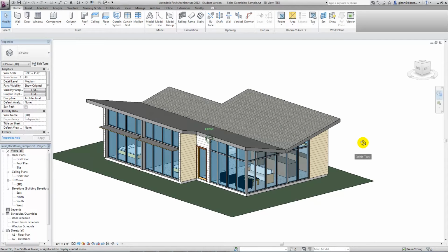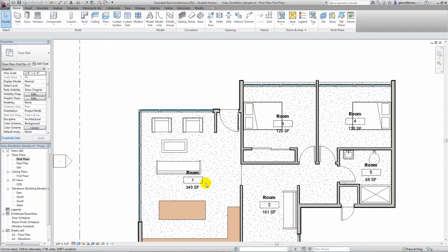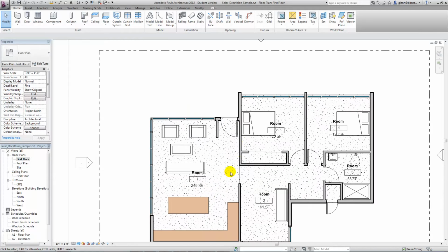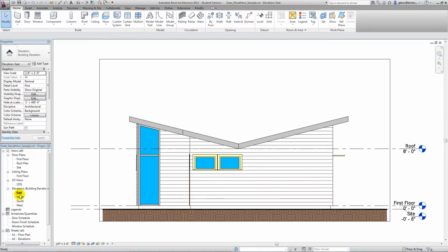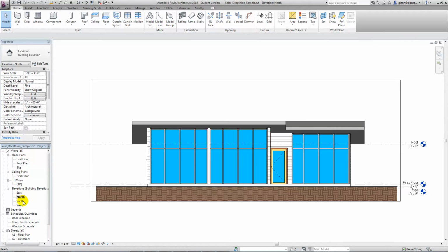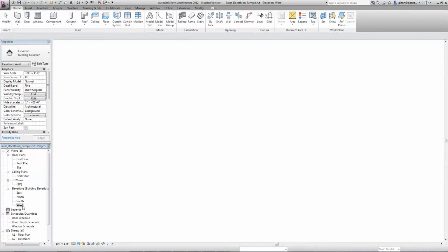And within this model, you see I've actually started to go through and put a lot of different information. I can look at it in the floor plan view, look at it in terms of all the different rooms, put furniture, figure out what the areas of the rooms are, really start doing a lot of design for that. But the beauty of the building model is not only do I have the floor plan and that 3D view, but I also have things like the elevations being created for me. Okay, and they're all out of the building model.